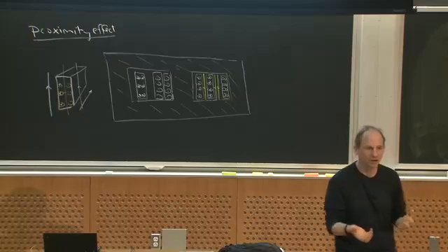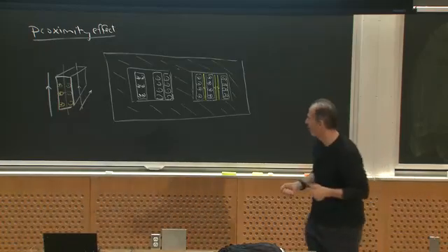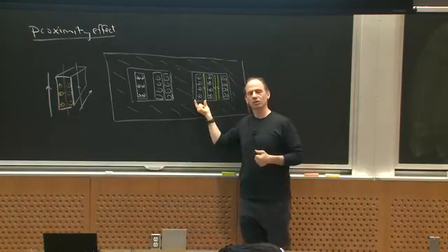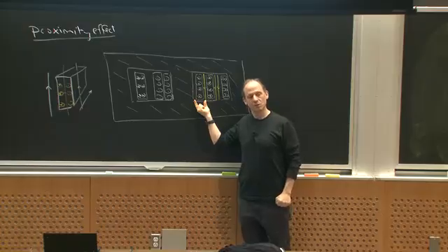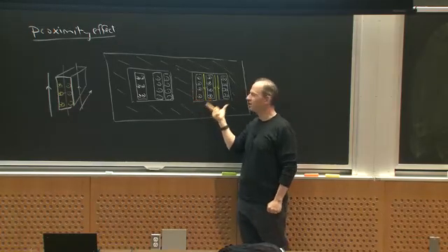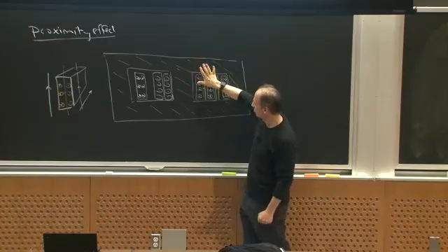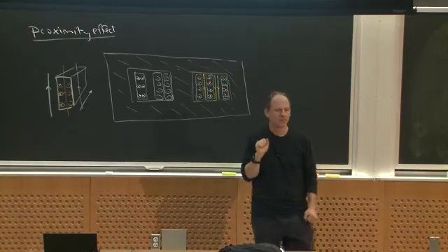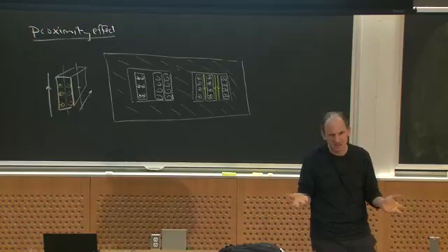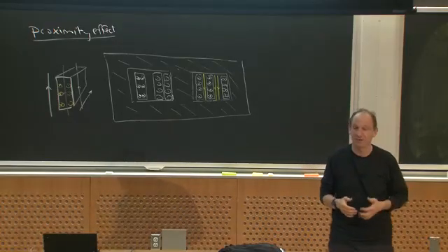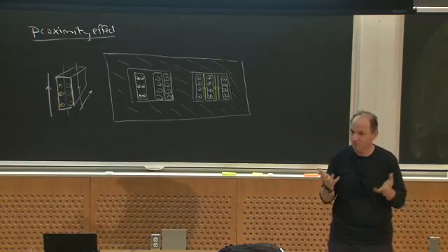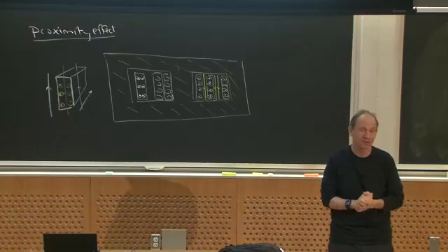So when does this occur? This occurs when you have conductors that are large compared to a skin depth, or on the order of a skin depth, and when you have many layers of winding such that fields from one winding are hitting the other. If you're designing something that's carrying mostly DC, don't worry about it. If you're designing a really high frequency transformer, you might want to start thinking about it because it can be a big effect.